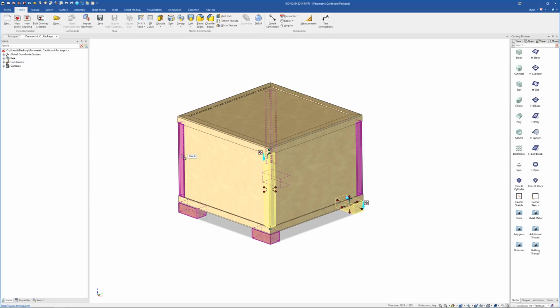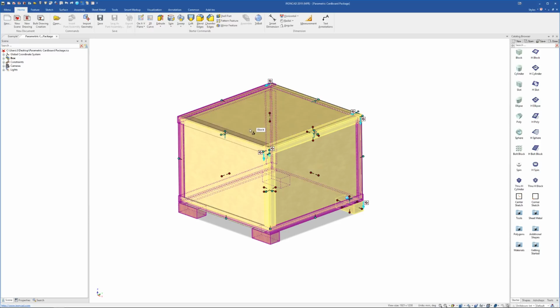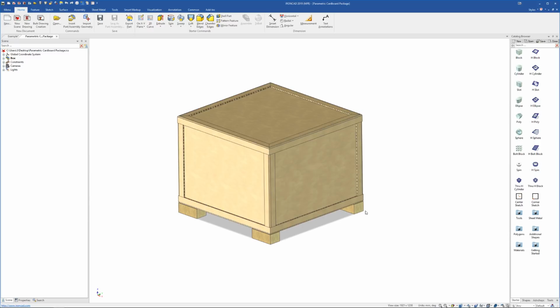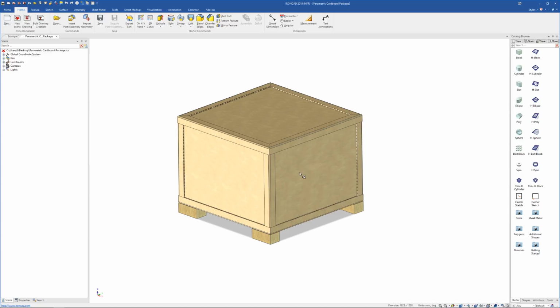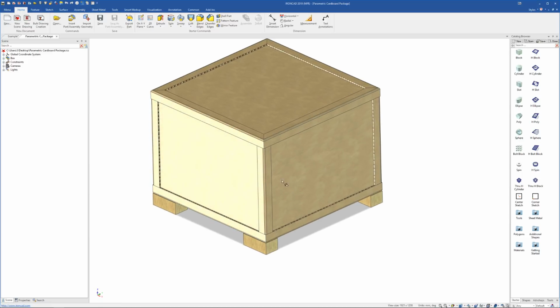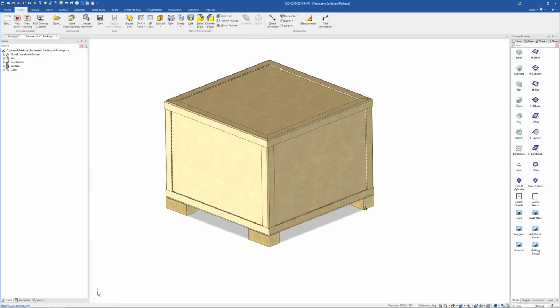If I hold down the Alt key, I can select straight down to these IntelliShapes without actually having to select through their part or anything like that. Whereas if I was over here and I just wanted to select this, I just held down the Shift key onto another part. Generally, it would go to the part level first. So that's just something to note. Just holding down the Alt key gets you straight down to that IntelliShape.